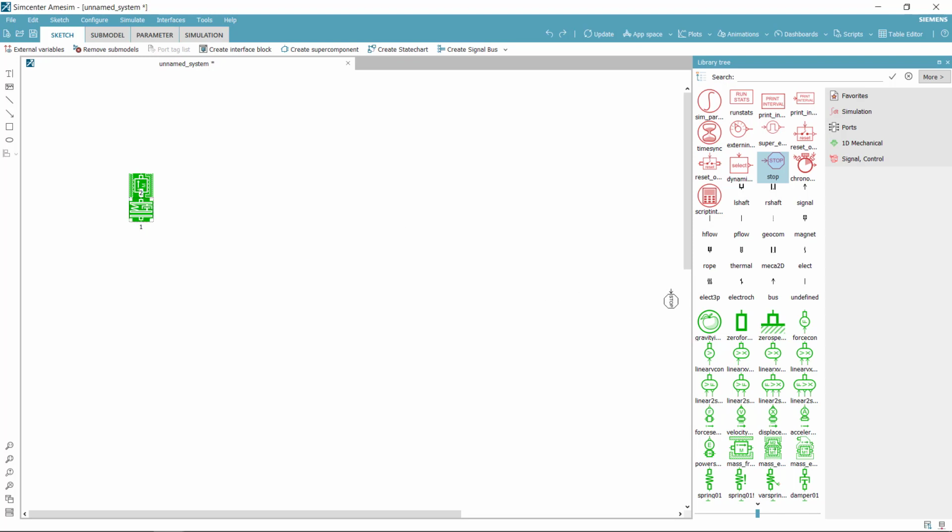There are two main ways of connecting components. The first is direct connection. Components with compatible ports can be directly connected without the use of lines. The second is lines. Sometimes it is not physically possible to connect two compatible component ports. In this case, the ports can be connected by using the line component. To use the line component, simply left-click on each port you wish to connect. Generally speaking, only use lines when they are absolutely necessary. This leads to a much neater sketch and there's less chance for bad connections.